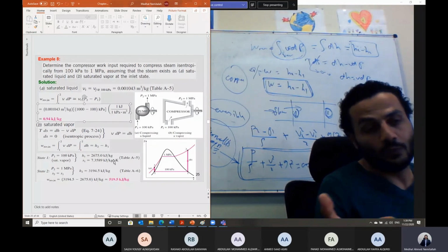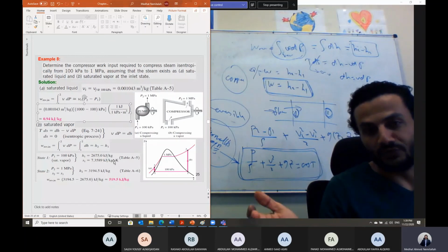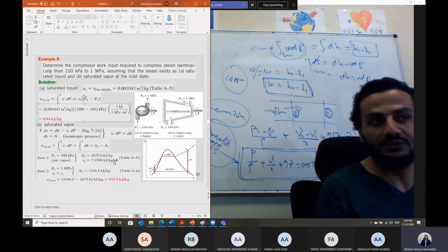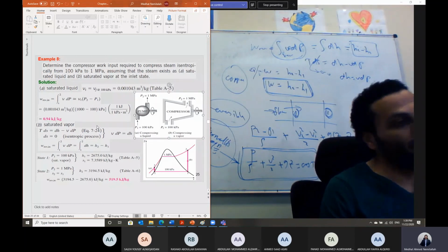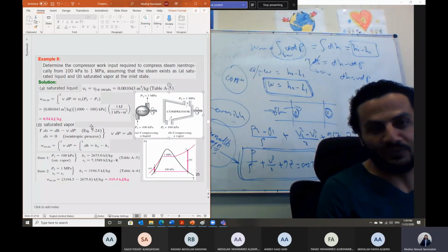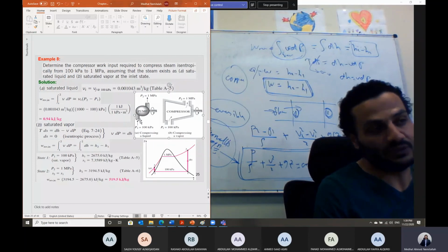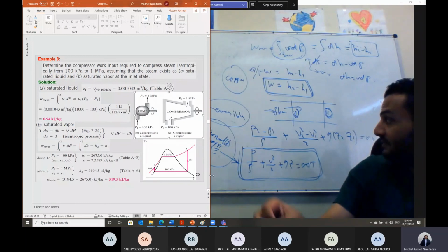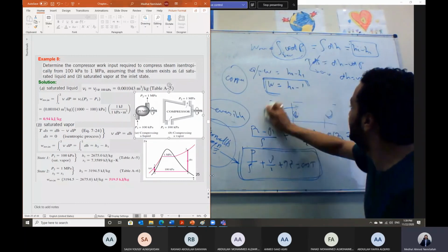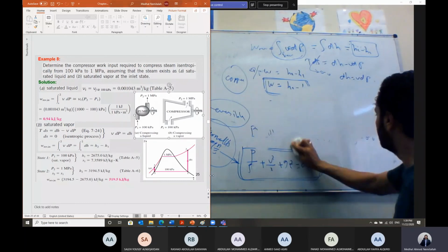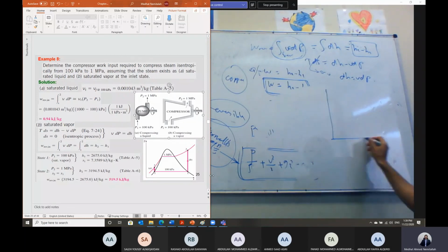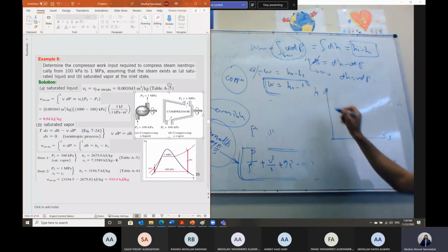And that's why we cannot just get rid of the condenser. It is better to convert the steam leaving the steam turbine to liquid. Then I can drive the pump with a very small amount of input power, because a pump or compressor consumes work. And you can look at this, Shabab, from the HS diagram, the Mollier diagram. If you look at this process on the HS diagram for the two cases, let's look at it.